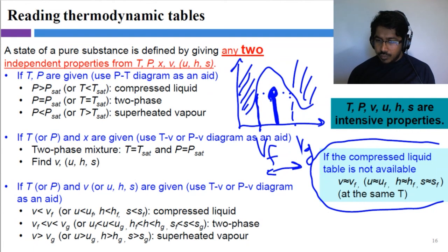Will P sat and T sat be provided? Menna, depending on the question, you will be provided with the pressure or specific volume or any other parameter. If you know the temperature, then you can determine the P sat. If you know the pressure, then you can determine the T sat, right? Likewise, you have to use the property tables to find P sat if needed.